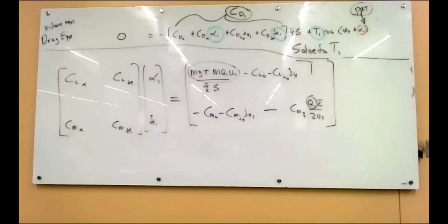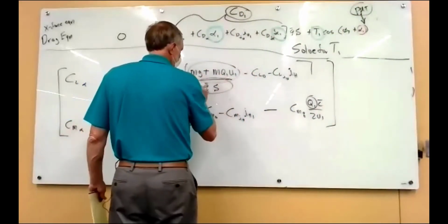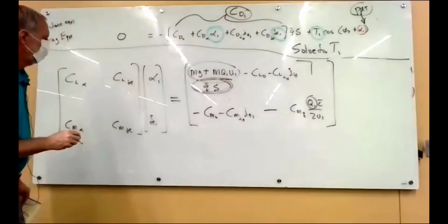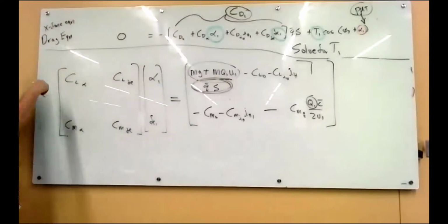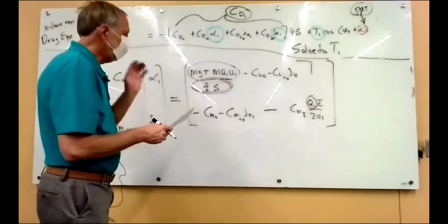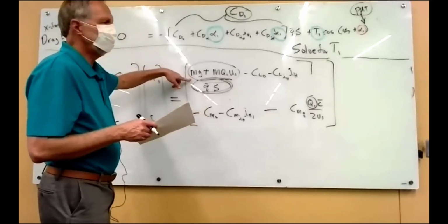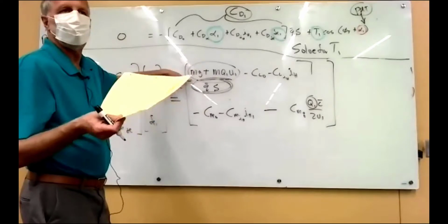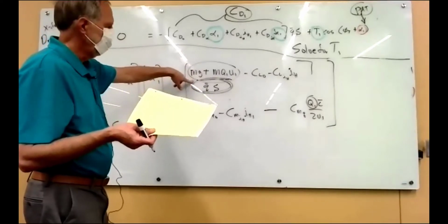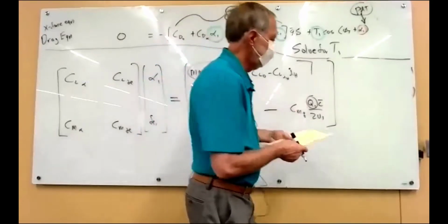So if we do that, and then for those of you on Zoom that I didn't switch back, I had forgotten to divide through by that because the CL terms are multiplied by Q bar S in the equation. So just to add that, that was a mistake. And now, based on what we just did, this term is just N times CL1, where CL1 is the steady state cruise lift. And then we plug in for Q1 here with the formula we just derived.